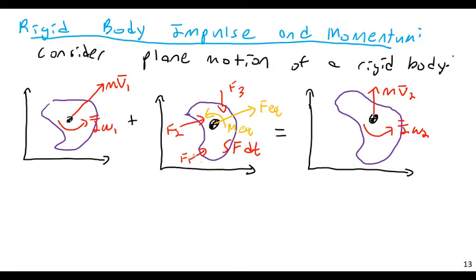I could turn all of these forces into one equivalent linear force, and then also add their tendencies to cause rotation about the center of mass by taking the cross products of the vector to the line of action of each force and the vector of each force, and I could find the moment therein. So again, we know this from statics, we can always reduce a system of forces into a moment and a force.